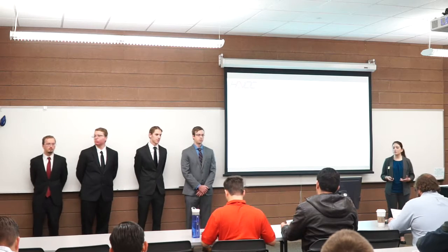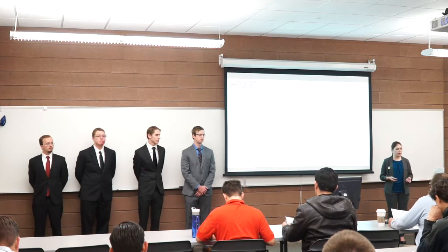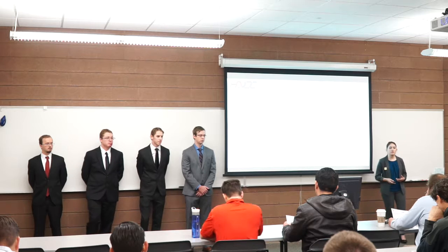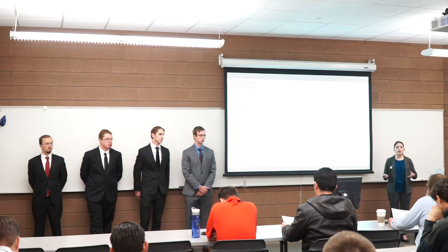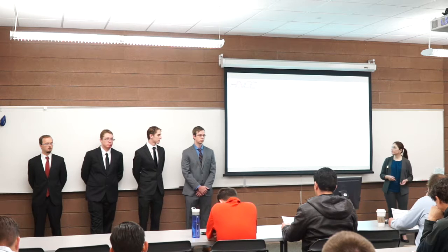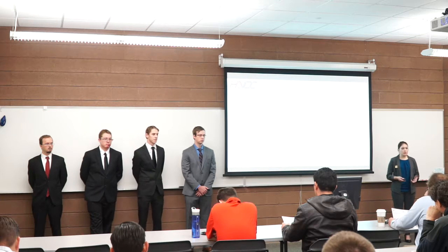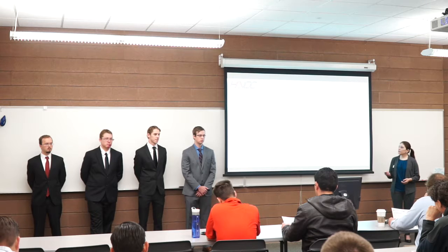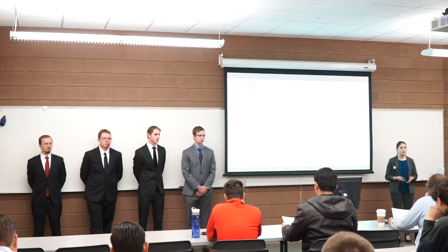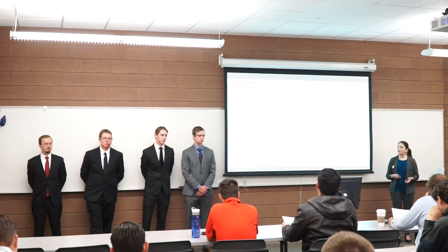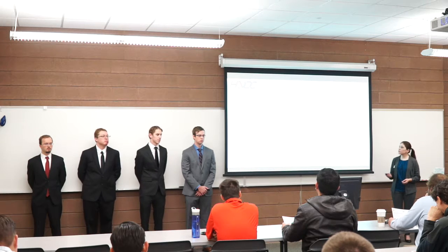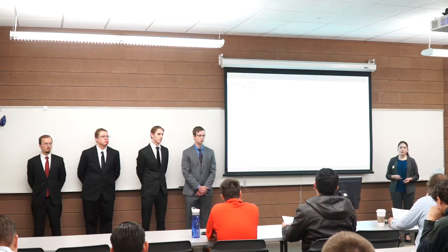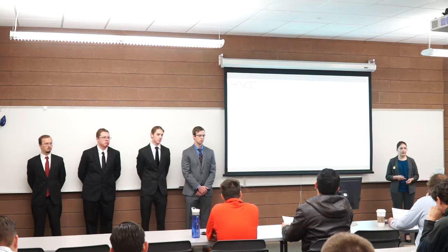So the equation of motion is a mathematical calculation that demonstrates the dynamic motion of the robotic hand when a force is applied on it. In order to get the equation of motion, we first have to take the kinetic energy, which is originally 1/2 mass times velocity squared, and expand it to the translational, coupling, and rotational kinetic energy.